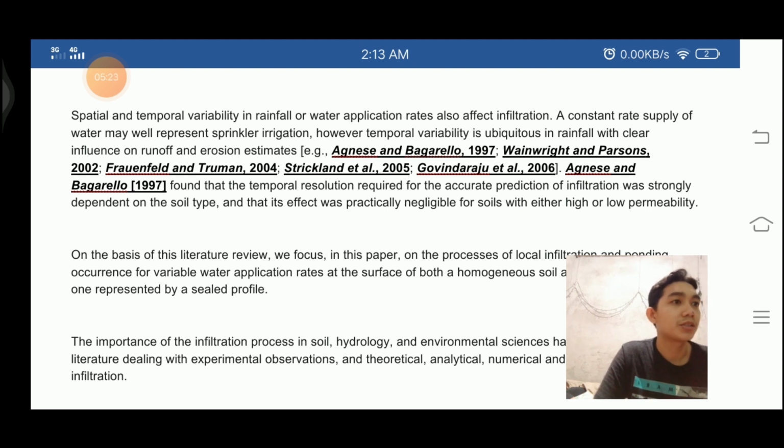By predicting the time of ponding during infiltration, we can know the type of soil in that particular place, and so we can study it. It is fundamental in hydrologic prediction of flood and erosion. Also, prediction of ponding time is fundamental in agricultural irrigation because this is where we will base our plans and what to apply to execute it.